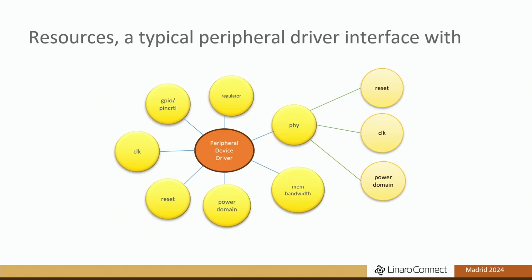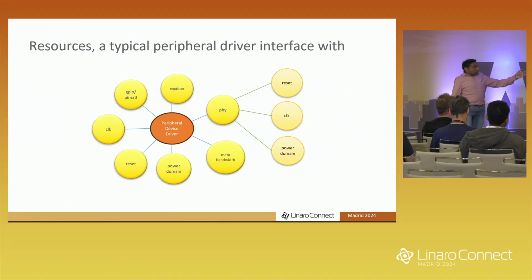This slide shows the complexity of a peripheral device driver. A peripheral device may belong to a power domain, so there will be a power domain provider driver that it needs to interface with using the PM framework. There may be a reset, it may perform certain resets, then it needs to interface with the reset control driver using the reset framework. The peripheral device driver may also need to deal with a bunch of clocks, and then it needs to interface with the clock driver using the clock framework, GPIO pin control driver, regulator